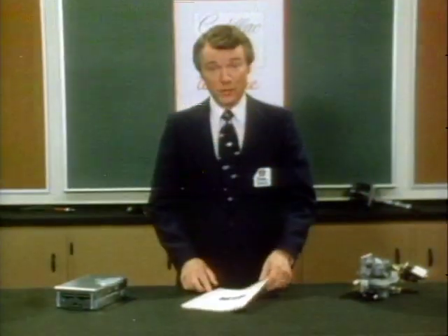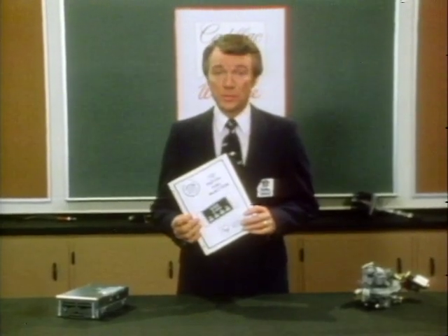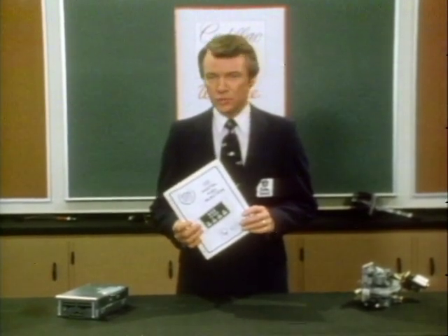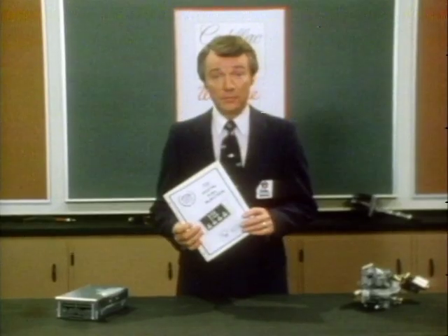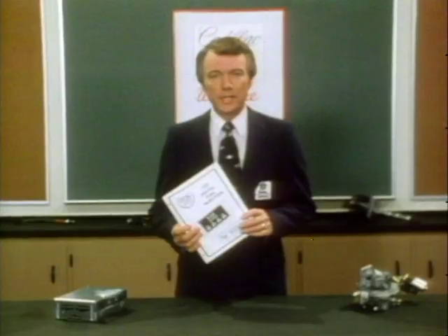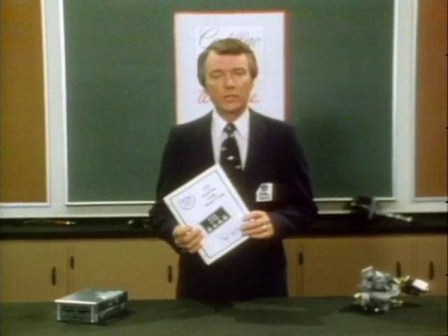The chart found on page 9 of the summary book summarizes input signal usage. It can be used as a reference to determine which signals are used by which system. A most important point to remember in understanding digital fuel injection is that the engine speed signal, intake manifold air temperature, and absolute pressure signals are used to calculate the base amount of fuel to be delivered. The remaining sensors only affect a correction to the base calculation.